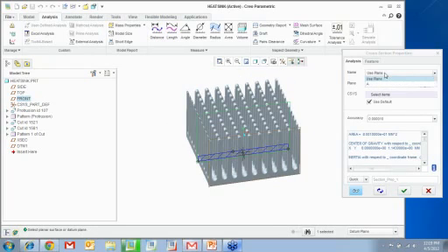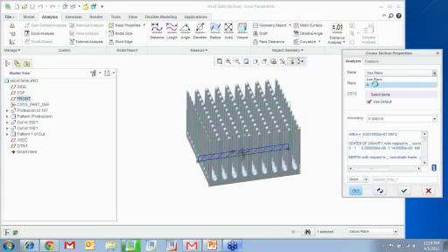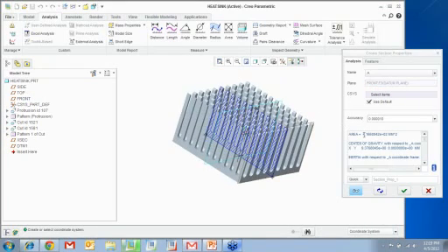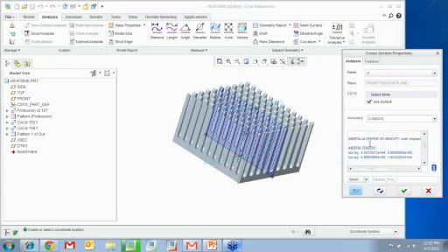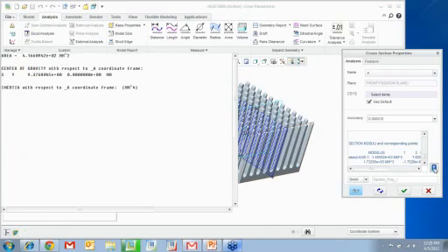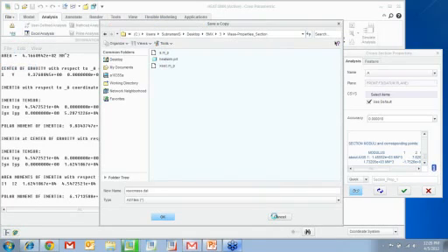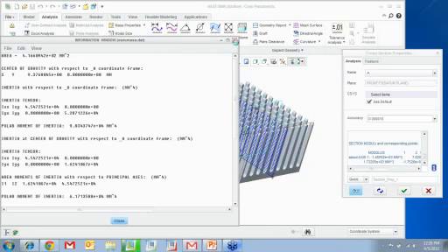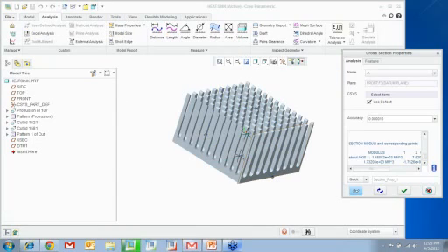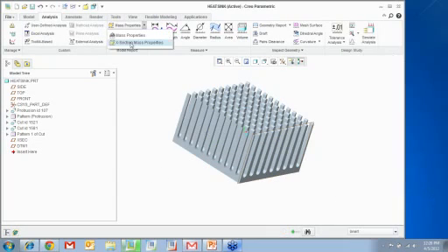that you can choose different planes, or you can also use the drop down and pick your cross section. So that's my cross section, and it tells me the area, center of gravity, moment of inertia, all those details right here. And I can click on this I, it comes out here, and I can also save it as a DAT file, right? So you have your cross-section mass properties that you can look through. All you have to do is dig here and find that.